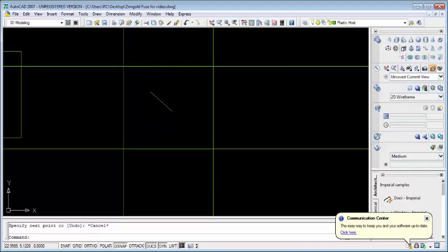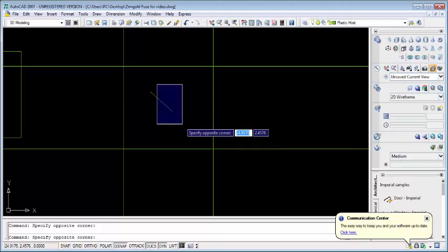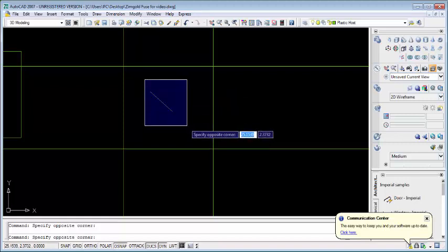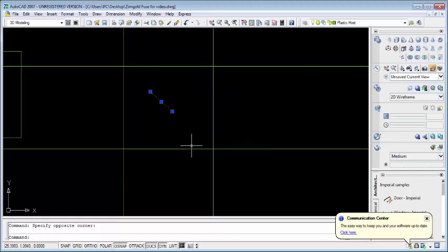Let me say there is a small line inside here now. I want to select this line. If I start from the upper right, and I come to the upper left, and I come to the lower right, I cannot select it, even though it's obvious that my cursor is over it. But if I can cover the object completely, it doesn't matter where I'm taking it from to select the object.